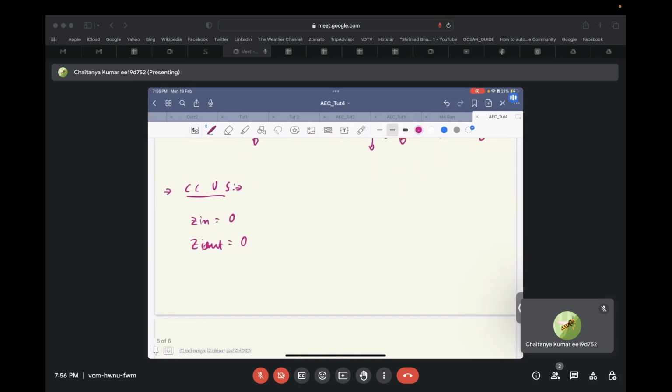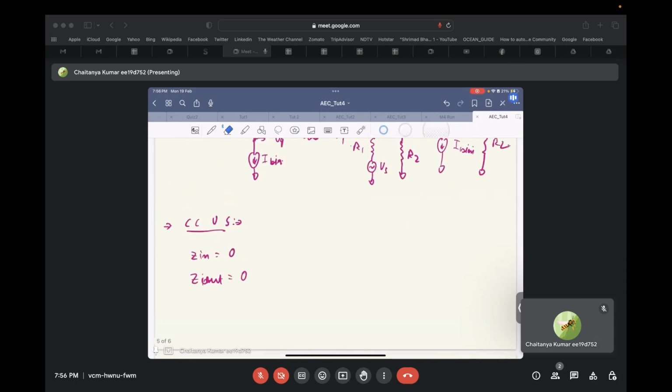We saw that what we wanted is, okay, before we go to that, all this analysis that we did for a voltage controlled voltage source can be quickly done by the concept that we discussed in the first tutorial, that is, if the circuit is in negative feedback and the gain of any kind of controlled source, a MOSFET in active region in small signal analysis is a controlled source, goes to infinity, then the controlling terminal becomes 0.